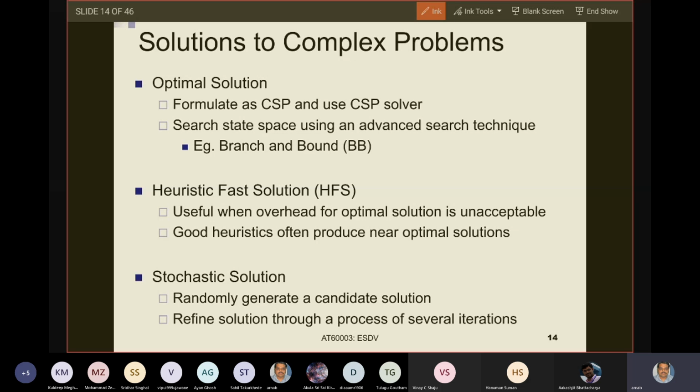For this hardware software partitioning problem, each task has a hardware cost and each task has a software cost, and you have a certain software execution cost bound, and I want to minimize the hardware area given that bound.